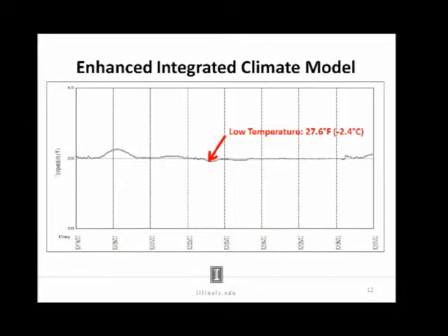So that kind of gives us an idea of what we should expect for temperatures there. And also, when we think about binders, here in Illinois, a 64 minus 22 binder is quite common. And that low temperature is minus 22 degrees C on the binder. So this is quite a bit higher than the minimum possible temperature that we would expect before cracking would occur from a 64 minus 22 binder.